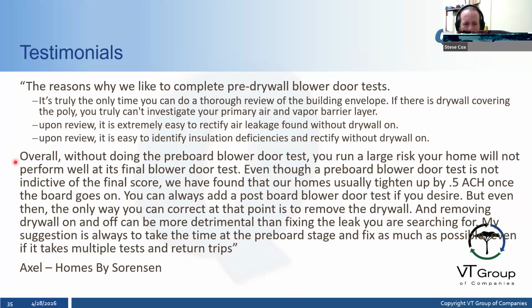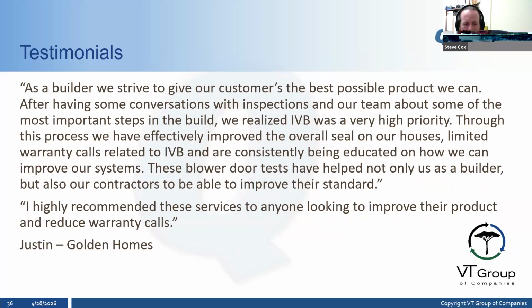He goes on to say, overall, without doing the pre-drywall blower door test, you run a large risk that your home will not perform at its final test. Even though the pre-board is not indicative of the final score, we have found that our homes usually tighten up by about 0.5 ACH once the board goes on. You can always add a post-drywall blower door test if you desire. Even then, the only way you can correct that is to take off the drywall. Taking drywall on and off can be more detrimental than fixing the leak you're searching for. So that's Axel's motive there.